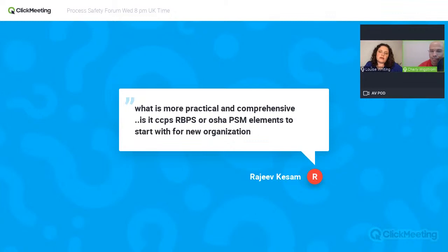Really. Yeah, I mean, from building or using safety cases in a lot of different locations, I would always propose to use risk-based process safety. Now, it's not easy. I've always worked on facilities which use risk-based process safety, but I've seen safety cases which are constructed compliance-based. So we've installed work orders for systems we haven't even installed on the facility because we think it's mandatory because of the framework. But there's no risk. We haven't identified it as a risk, so it's not built into our design. Yet because we see that the corporate wants us to do this activity, we've put these work orders in. And then when the guy goes to execute them, he's just closing them out because he knows that system doesn't actually exist.